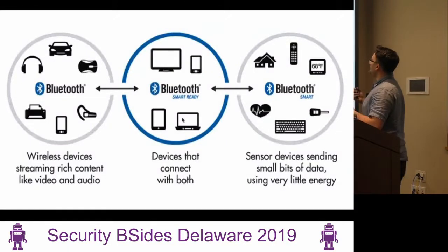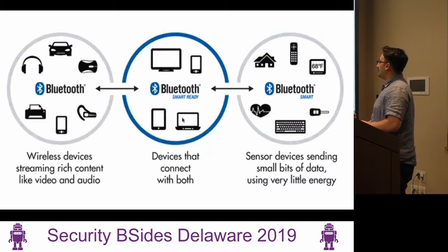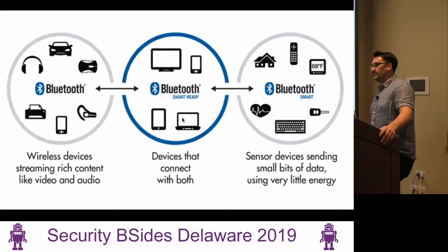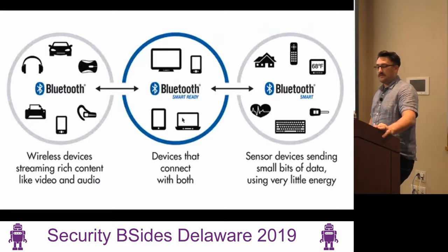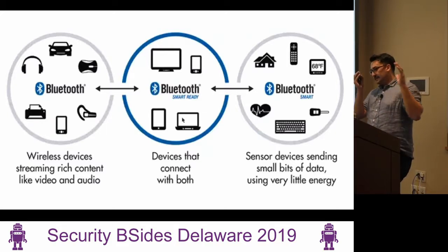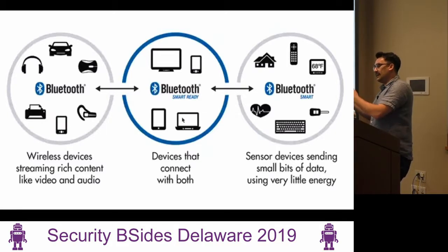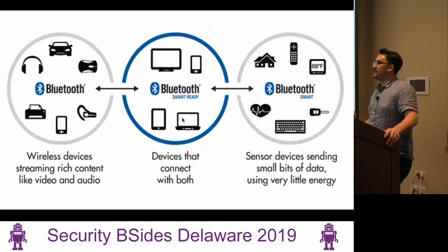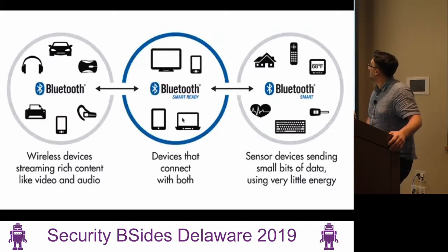One of the first things I came across when looking at Bluetooth Low Energy is what's the difference between what we've been calling Bluetooth for 5, 6, 7 years, and what's this Smart Ready and Bluetooth Smart. So very simply, your regular Bluetooth is for what we'll call enriched data, so large amounts of information, like a VoIP call or your Spotify playlist. Bluetooth Smart Ready is a device that can have enriched data like those calls, but it can also be a mesh network thing. It can create a cluster of other BLE devices, so it's got both abilities. And then Bluetooth Smart is where they've completely dropped the traditional Bluetooth protocol, and they are only BLE. So that's Bluetooth Low Energy. That's where the smart idea comes from.